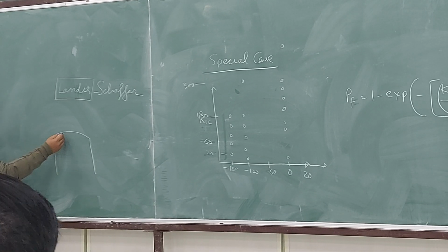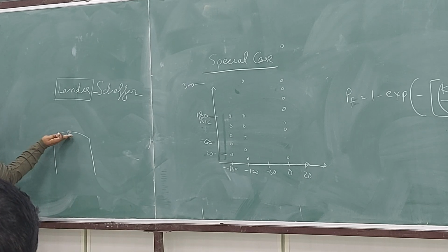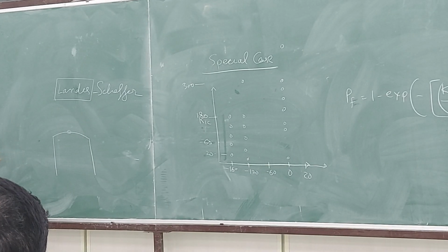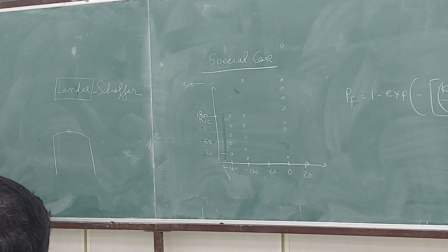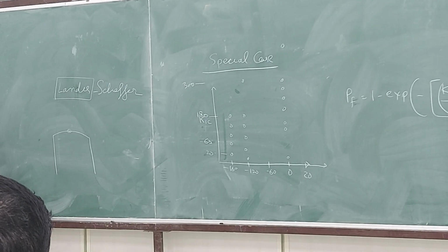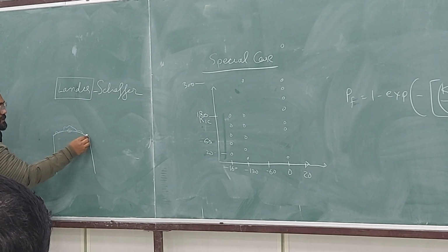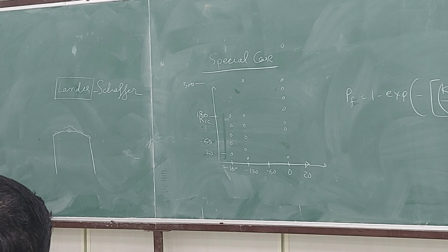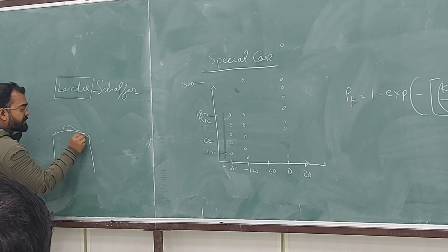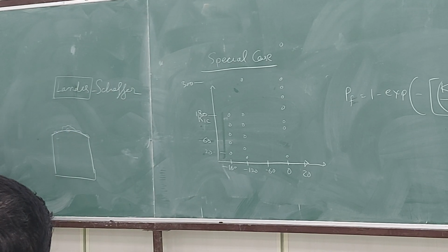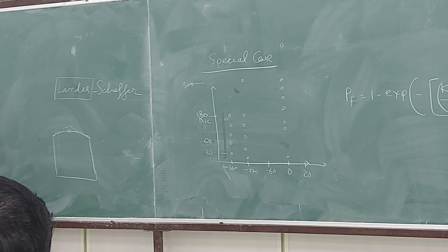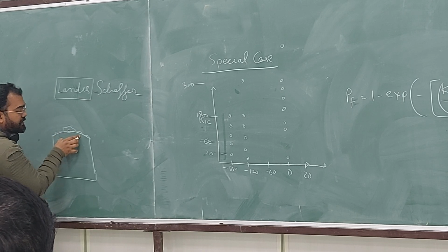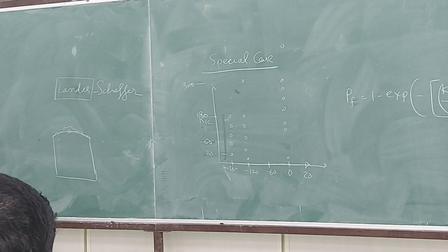Okay, so constraint is highest in the center, so the crack propagates not uniformly, it propagates more in the center, less at the surface. So you get a tongue kind of shape. Not exactly like this, but in experiments you will see something like this. It's not that uniform. So the crack front is represented by this line, and assume this to be a broken Charpy sample, fracture sample, whatever it is. Plastic deformation happens, and then there is a trigger point, and then it breaks.